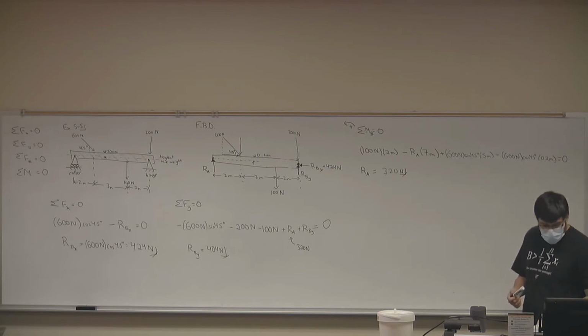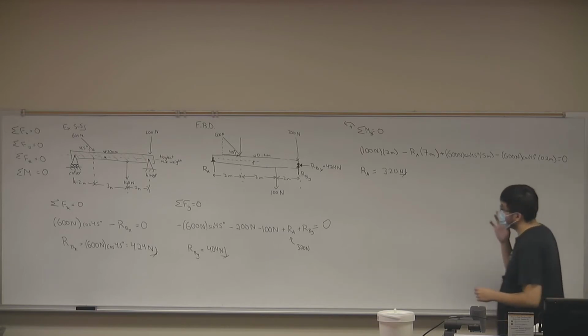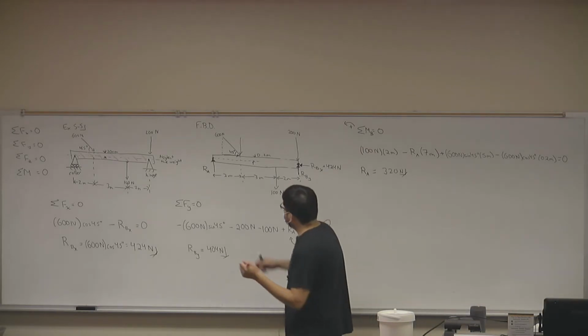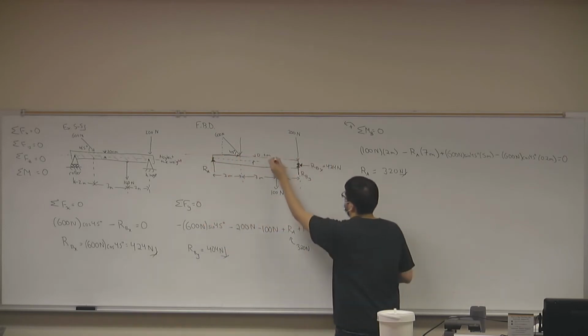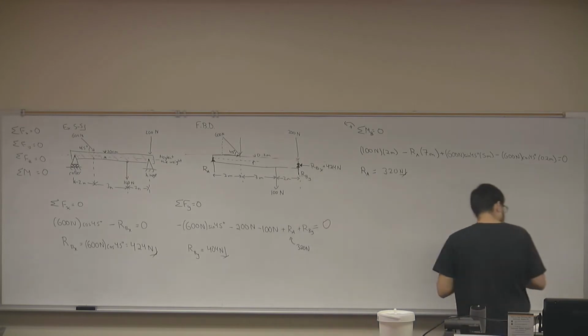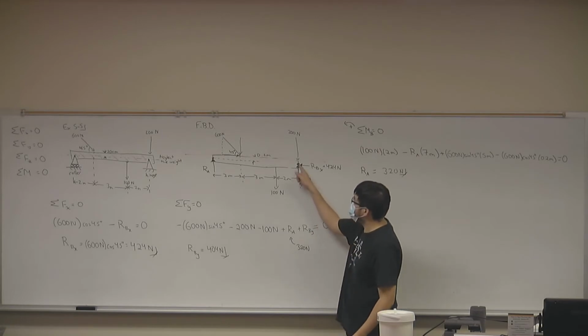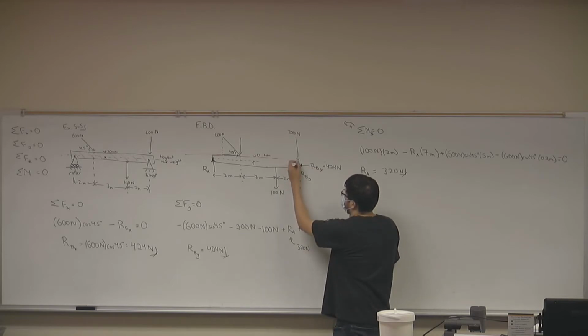So any questions with this system? No? So with the x component of 600 newtons, it's 0.2 meters, but why is that in there again? Remember that moment is any force that acts at a distance, right? So we have this line of action, the straight line, a line of action of this force. And you want the closest distance, the perpendicular distance between your point and the line of action. And that perpendicular distance, notice, is 0.2.